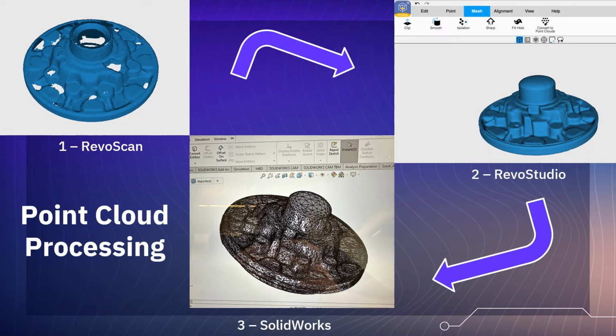The next step in the reverse manufacturing process is to merge the raw point data from the 2 scans and transform it into one STL component file. This represents stage 2 on the slide, Revo Studio. Several software features are utilized, including clipping, isolation, hole filling, simplifying, alignment, and meshing. The alignment tool is a process combining the 2 scans into one single scan and is done first.